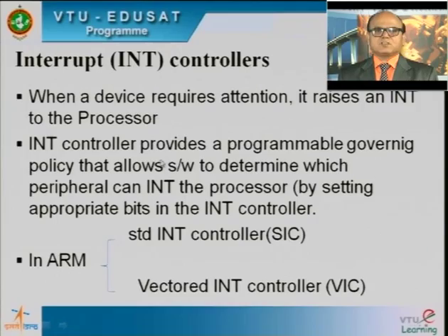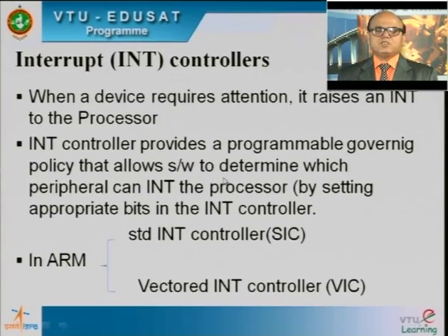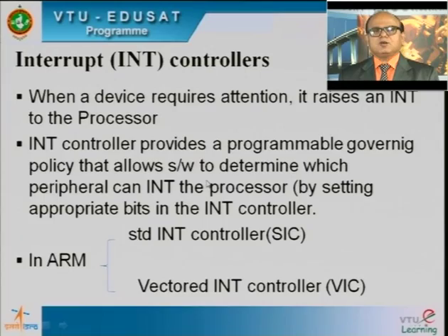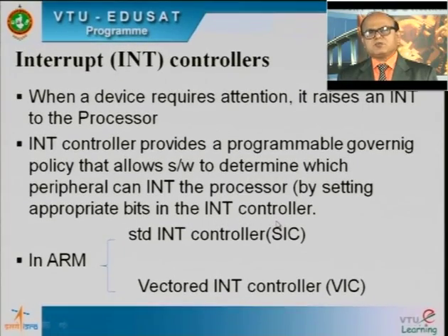The interrupt controllers provide a programmable governing policy that allows the software to determine which peripheral can interrupt the processor by setting the appropriate bits in the interrupt controller. So the interrupt controller has a register, and each bit of the interrupt controller can be set or reset.